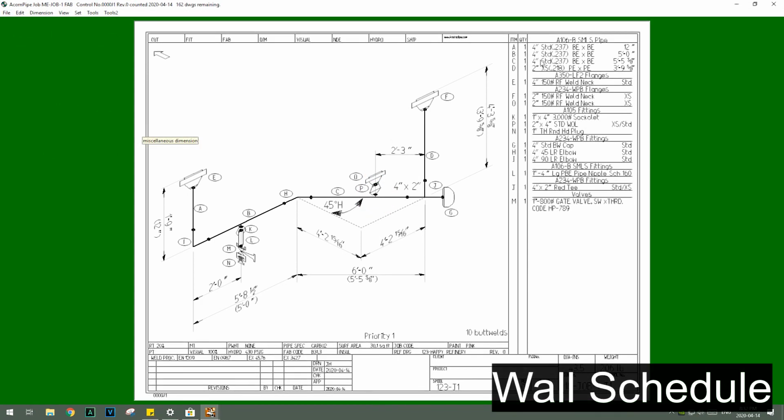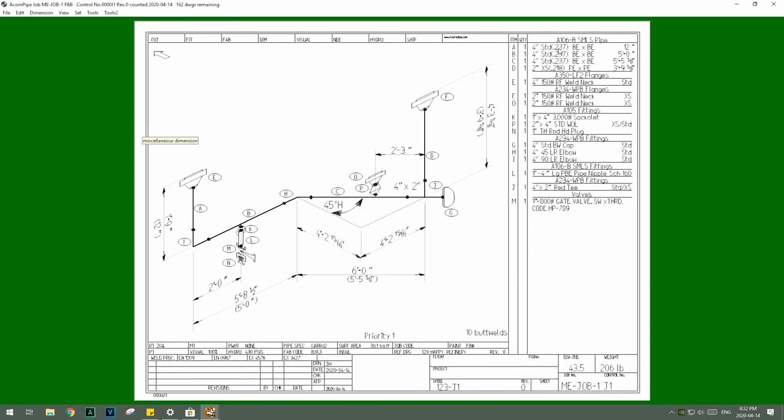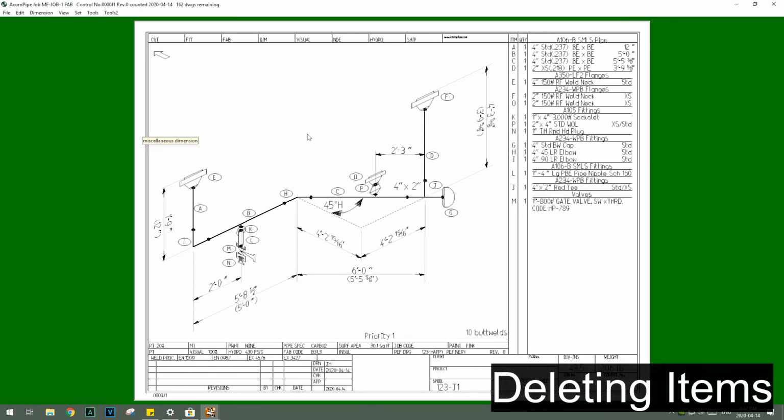So you can see it gives you the wall schedule, and then brackets after it, it tells you the actual weld thickness or schedule. So 4-inch pipe standard wall is 0.237 inches thick. Some items it may just tell you what the schedule is. And there may be a change in the schedule, such as in this weldolet. Actually, yeah, that's a little bit more confusing there. But anyway, say I wasn't happy with what I'd done here.